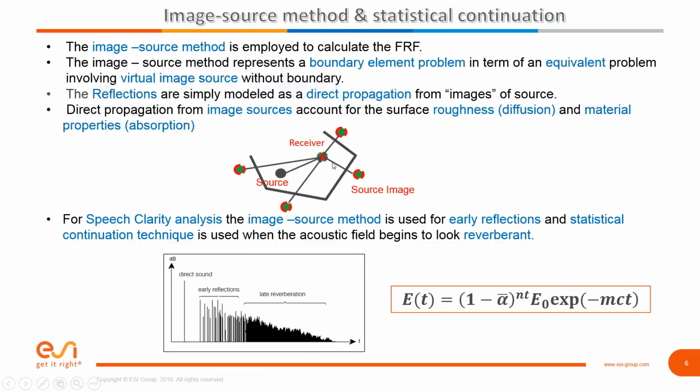So this is the basic way that we're simulating and coming up with a problem. You've got a source with a direct line path. You can generate source images corresponding to the reflected surfaces. They have a reduction of magnitude and a change of phase according to what's on the surface. And you're adding those up with all their relative phases and getting a total answer, both for the steady state solver and for the speech clarity, the transient version.